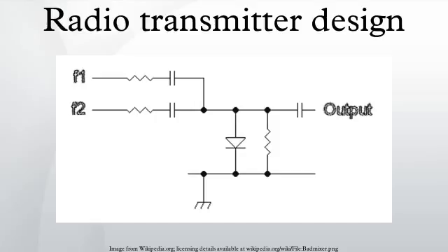Phase modulation is mathematically equivalent to direct frequency modulation with a 6 dB per octave high-pass filter applied to the modulating signal. This high-pass effect can be exploited or compensated for using suitable frequency shaping circuitry in the audio stages ahead of the modulator. For example, many FM systems will employ pre-emphasis and de-emphasis for noise reduction, in which case the high-pass equivalency of phase modulation automatically provides for the pre-emphasis. Phase modulators are typically only capable of relatively small amounts of deviation while remaining linear, but any frequency multiplier stages also multiply the deviation in proportion.